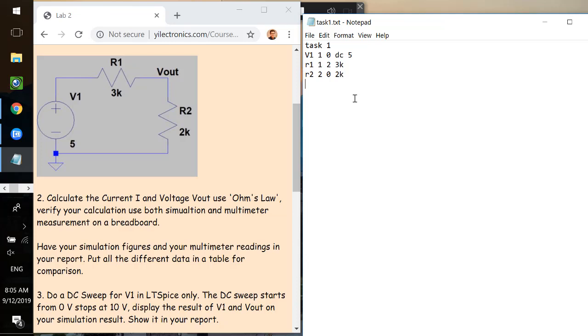So we can directly use time domain analysis, like we are directly connect this current meter in or voltage meter to an oscilloscope. So we do dot tran, which is transient analysis in time domain, from 0 second and stop at 1 second. And every 0.01 second, we plot the point of the curve.